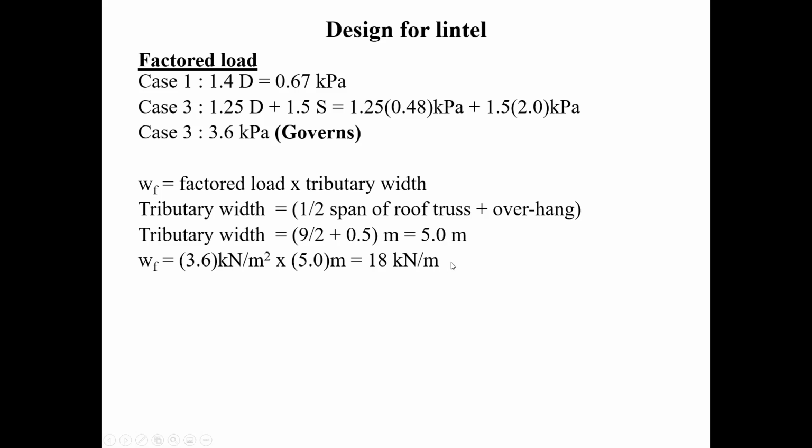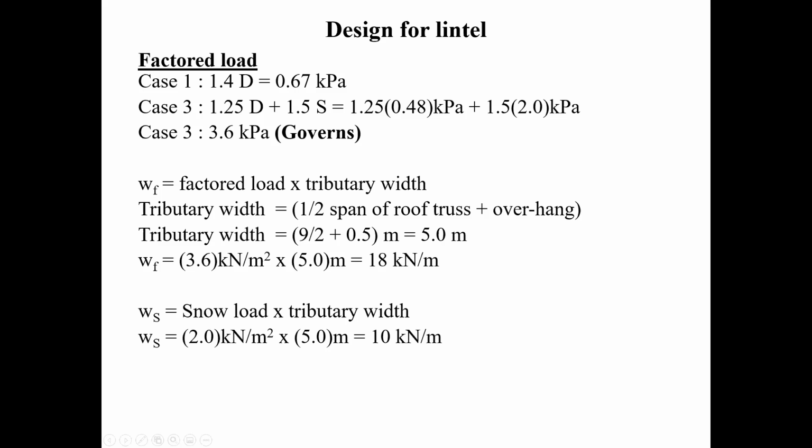Now, guys, what's a lintel, basically? What's another term for a lintel? It's a beam, all right? So what choice do we have when it comes to beams? When you were designing the built-up beams for the floor, you're doing the same thing for the lintels. You're going to be designing a built-up beam for the lintels. That's what we normally do, unless they're extremely wide spans and you don't have the room to put like 18 layers, or plies, I should say. So you're basically just designing a beam. This should be a review and not necessarily a new concept.